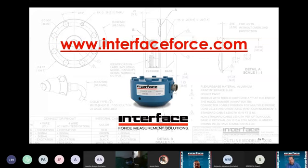So I think it's imperative that if you aren't familiar, please refer to or ask for our installation instructions, at which point we'll have clear guidance in terms of recommended torque values and proper methods to attach to it. Sometimes it's easy to over torque them. Again, these load cells are designed to see axial loads, and oftentimes people crank on things and you transmit too much torsional load through, and now you've got performance issues that may not show up right away.